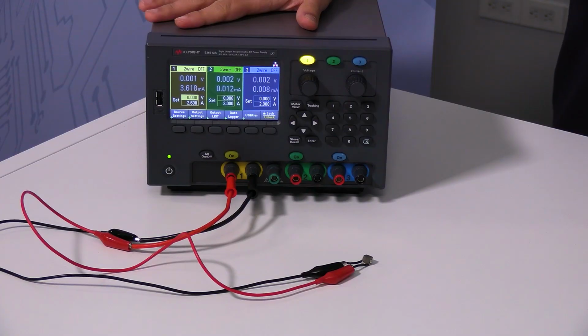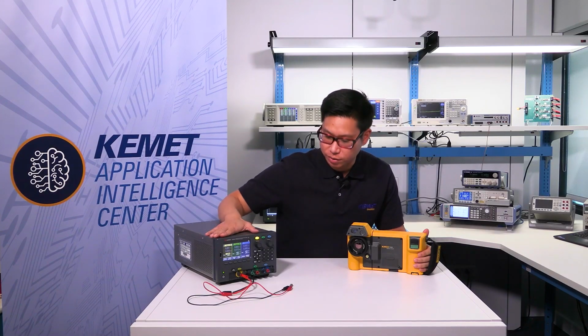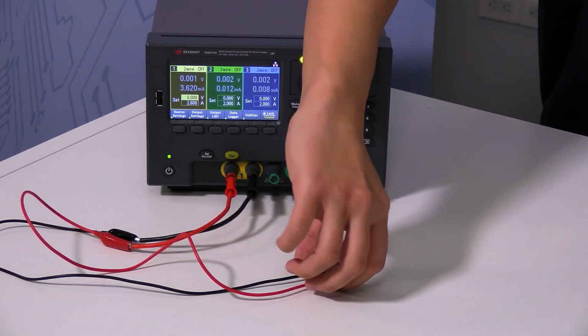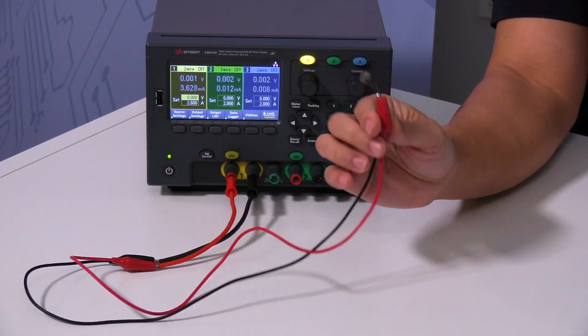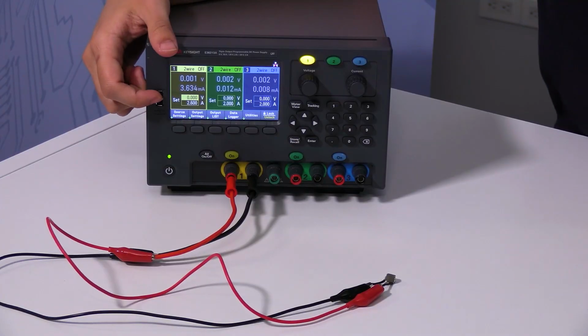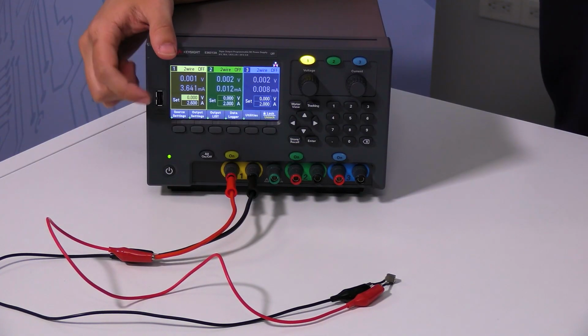William, you gonna help me out with this? Oh yes, we could test rated current pretty easily with just a power supply. So with the power supply, we're gonna make sure that we have it set to constant current mode. And in order to set it to constant current mode, we're gonna set the max current of the power supply to the value of the rated current of the inductor. So in this case, I have a 2.6 amp rated current inductor in my hand. So I set channel 1 to be 2.6 amps.